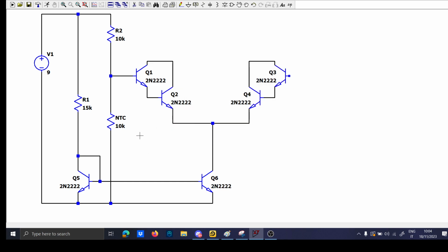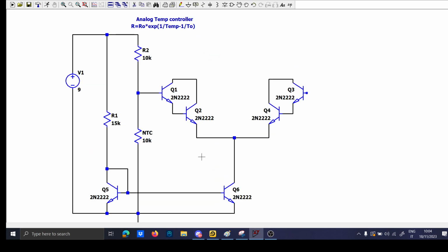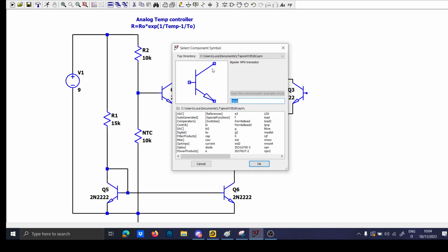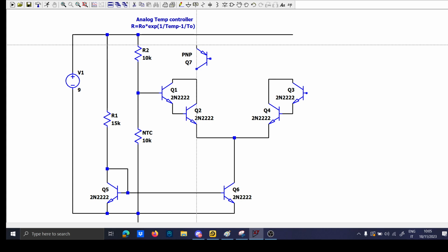Let me choose the transistor here, and also put it to ground. And now the same to this side here, but we have to do it with a PNP, just because we have the voltage on this side, and it is a high side. So the trick is, when you have the voltage on this side here, it is better to use a PNP, because remember that in a PNP you have to provide an emitter voltage which is higher than the base voltage.